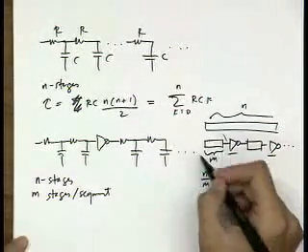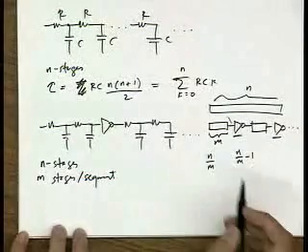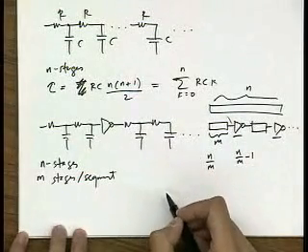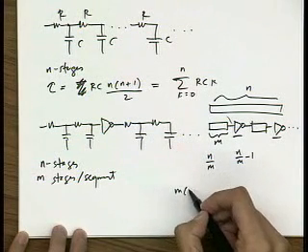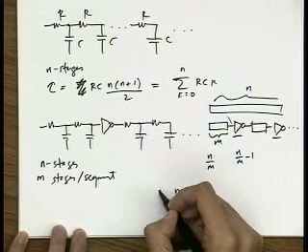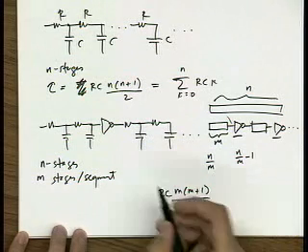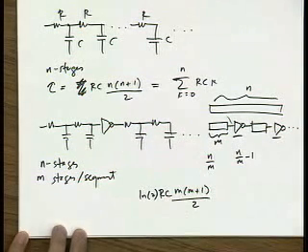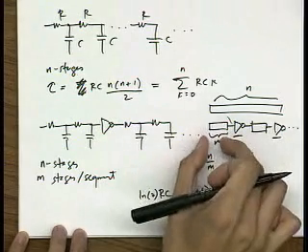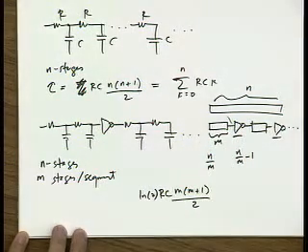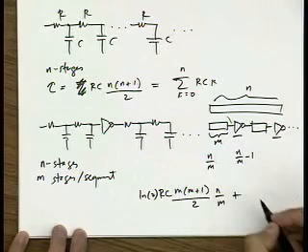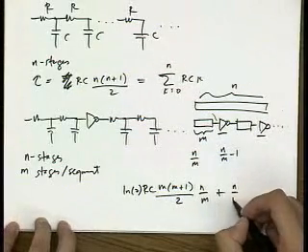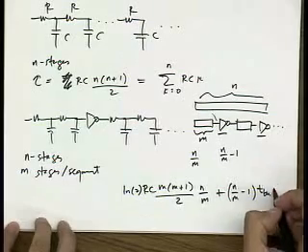So what's the delay of one segment? The delay of one segment is (m plus 1) over 2 times RC. And since this is not a time constant but a delay, you have this ln of 2 factor there. But this is for one segment. If I sum all the segments, it'll be n over m times that, plus the n over m minus 1 times my buffer delay.